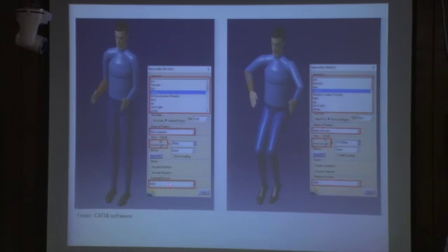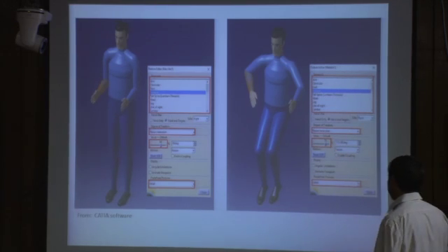Then the predefined posture is initial. Initial standing posture is there. Again you can directly change it to sitting, sit, stand or kneel. This type of other posture also you can go. Then here is that example. So if we are modifying that particular body joint angle, then this type of different posture we can create using manipulation of position of different body segments by changing the angle of body joints.